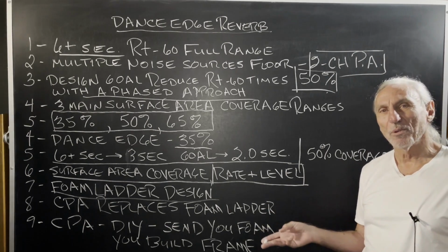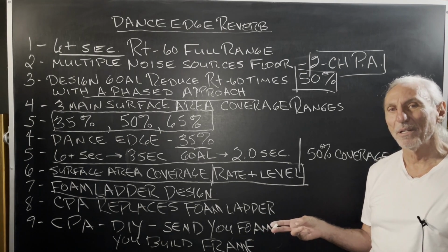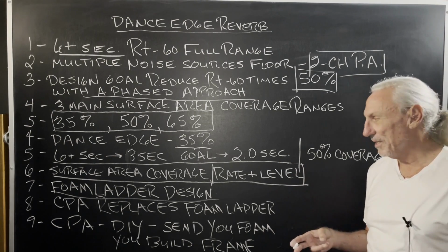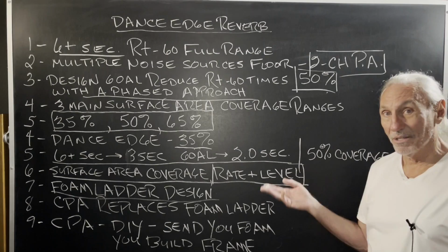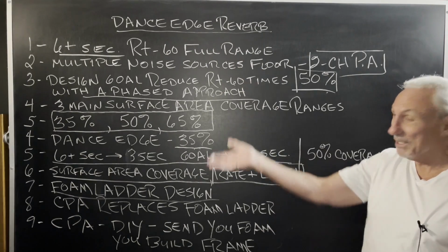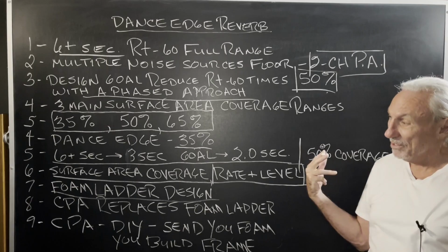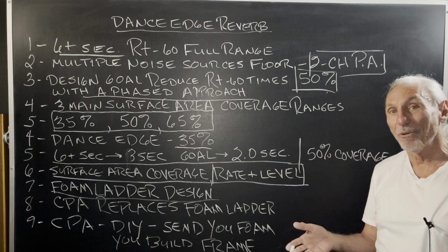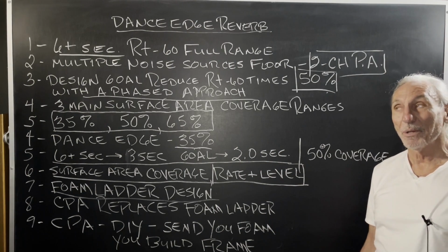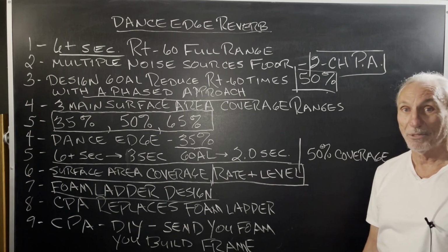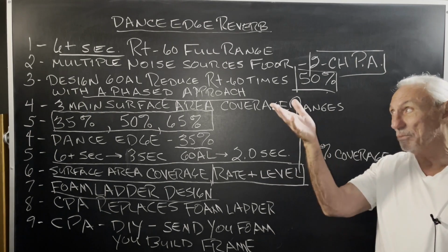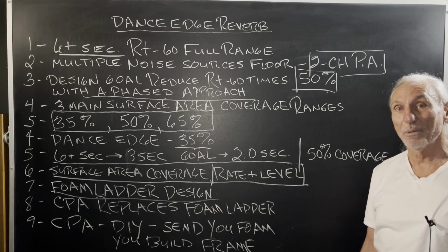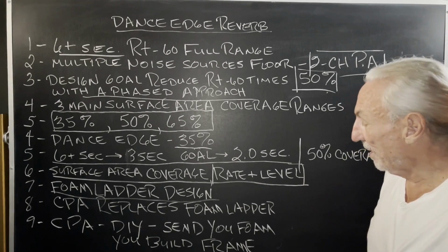And I think if I remember looking through the video and listening to the video, you can hear the remaining RT60 time in the room. You can still hear it. So, of course, I'm fussy. I want it dialed in perfectly because we have the ability to do that. But it's always what I want for the room and what the room needs versus what the client can afford and what they're willing to give up in space requirements, or what's even available in space requirements to give up. Churches have so many windows and ornamentation, we have no room to treat. The rooms look pretty and nice, but they sound horrible. Makes no sense to me.